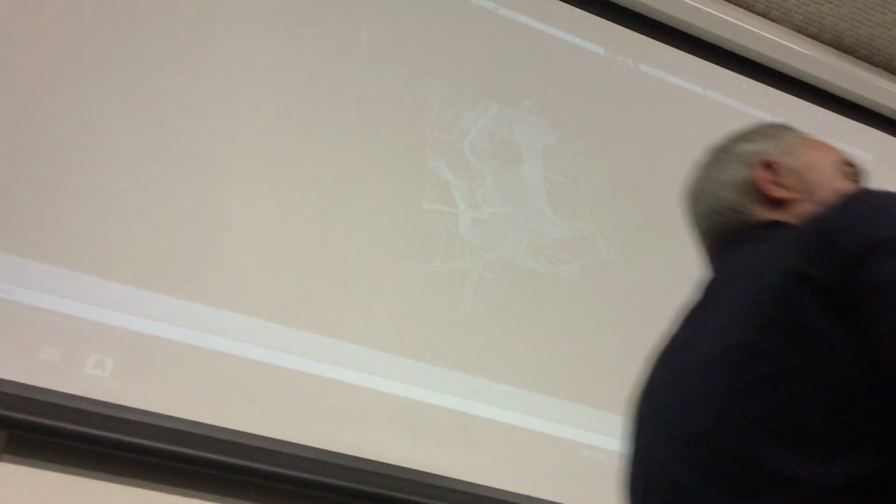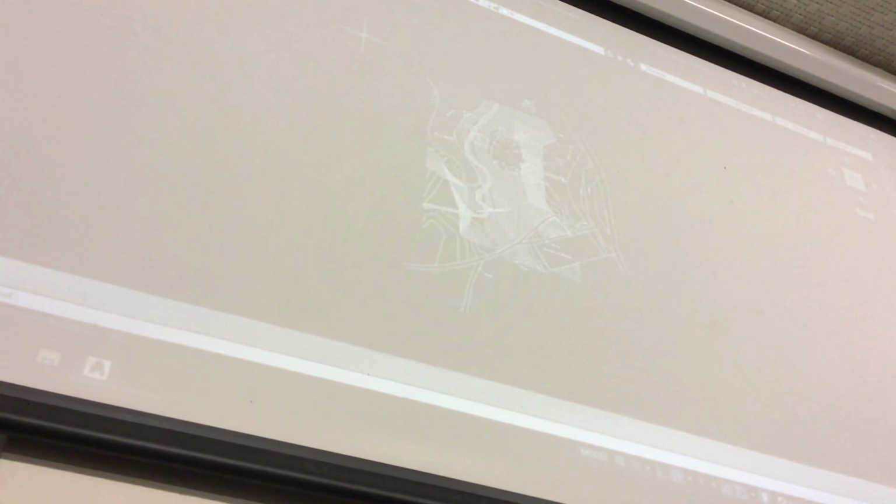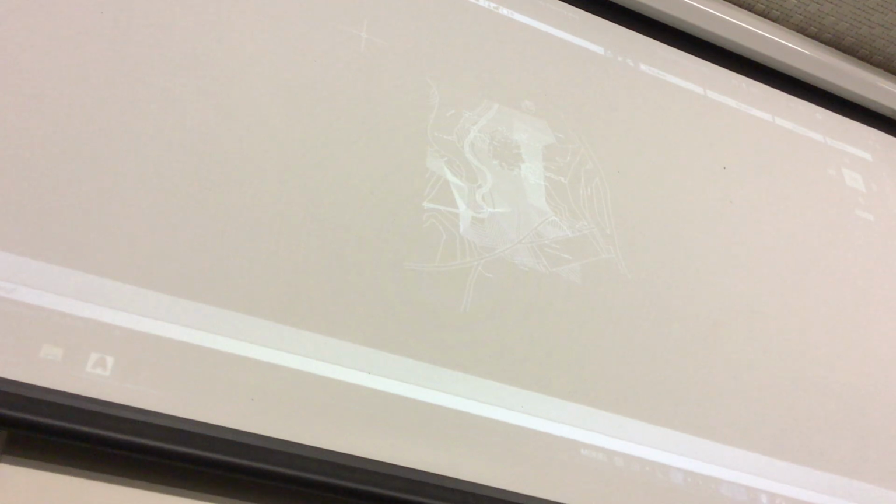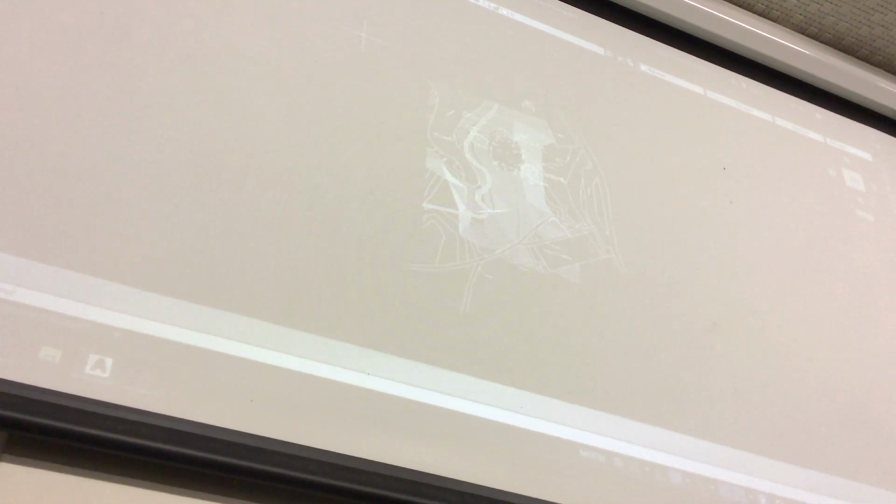You need to do the maths at the scale to work it out. 3.5 is most of the text, and 2.5 is the contours. We always do contours in smaller text because it's not as important on the drawing as the actual design or the features we're trying to show.